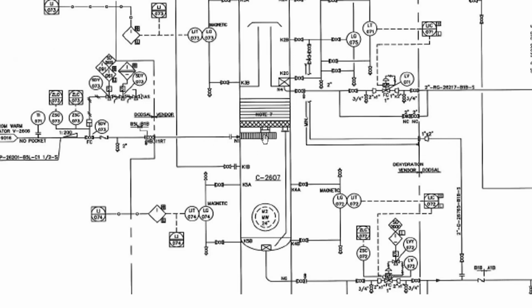It will change the velocity and direction, and with a sudden decrease in velocity, heavy liquid particles settle down in the system. Here also one internal part is there, and then a demister pad is there. So all internals are supporting removing the maximum liquid particles from the sour gas.